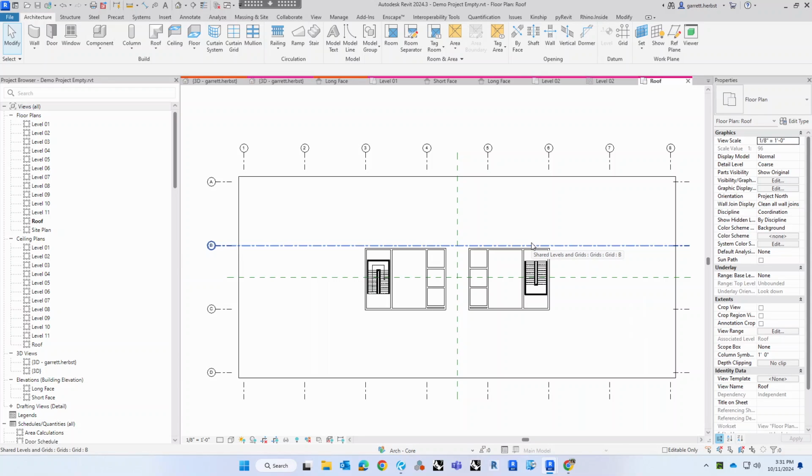So again, this kind of looks a little bit messy, but that is okay. I'm just going to quickly check my notes and all that good stuff. Within the Autodesk family inserts, you can find a lot of that equipment if you want to be really specific. But ultimately, what we typically do is just put massing in there. We'll get the dimensions from the engineer, and then we'll just put massing in there to make sure that everything is appropriate.